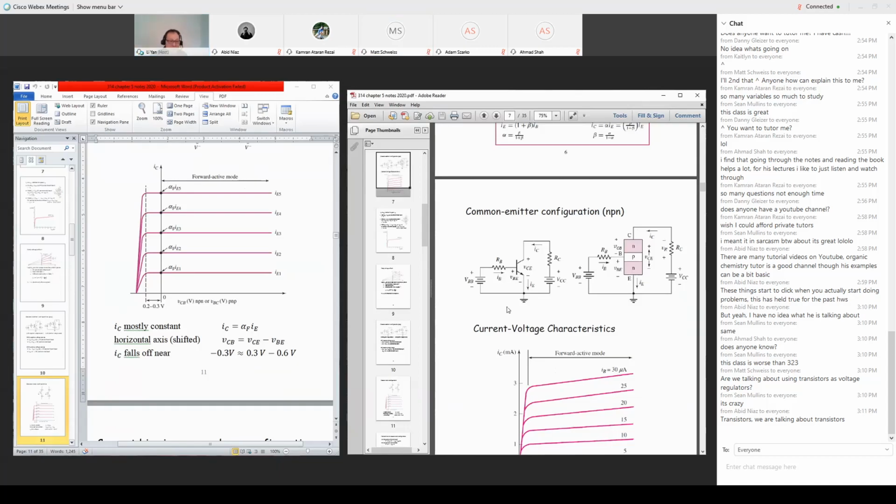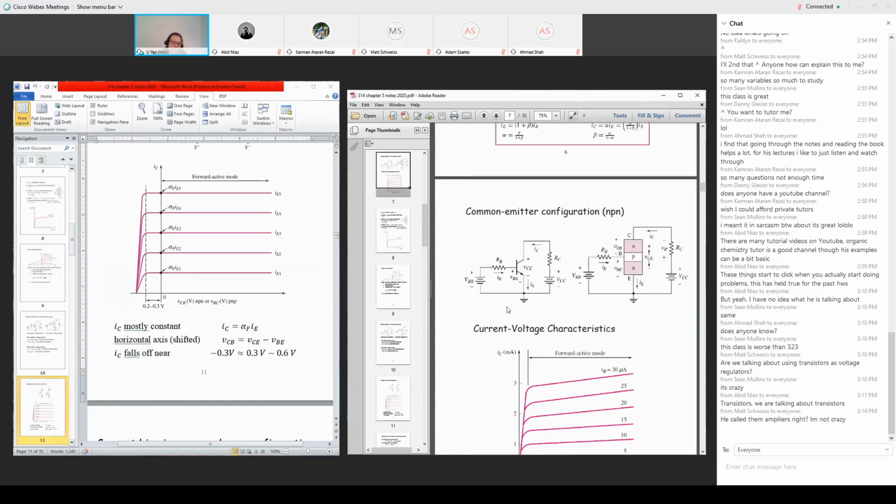Correct. Because chapter 5 only says you operate the transistor at its middle point based on the DC voltage. And the middle point, in chapter 2, we call the quiescent point or bias point. Around the bias point, you inject the AC signal, and you see the AC signal gets amplified. That part of the discussion, indeed, is in chapter 6.